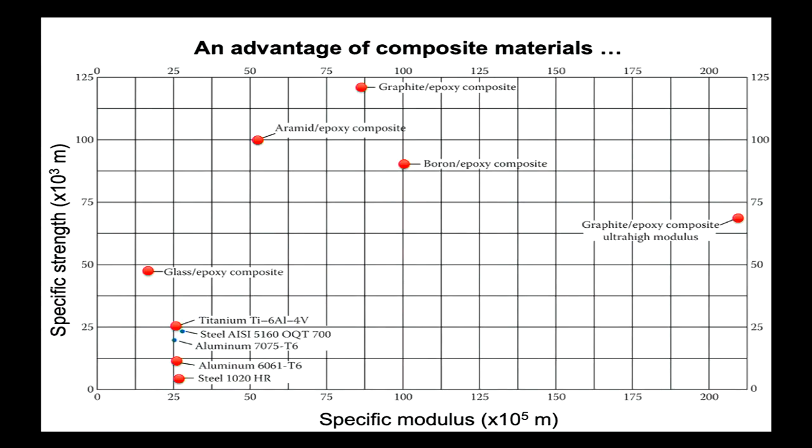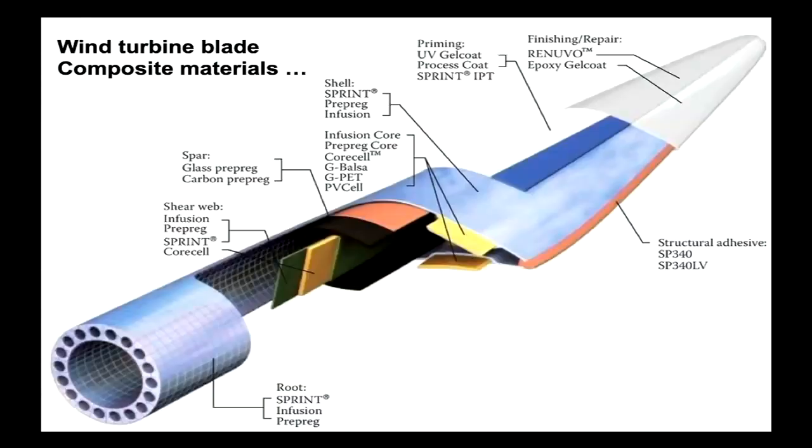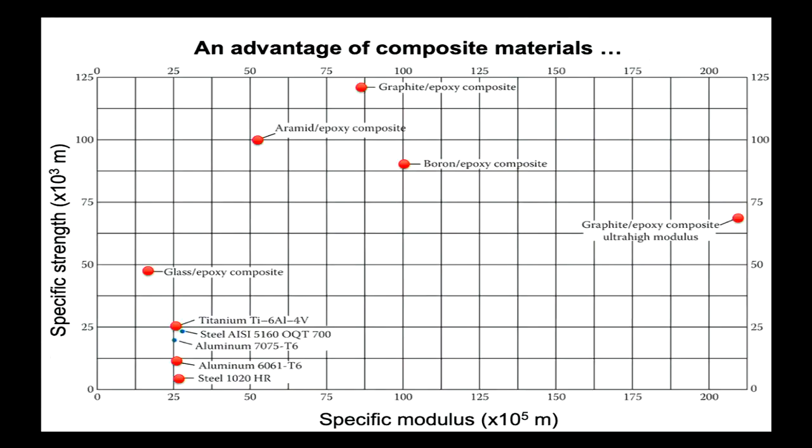This is a slide that's given you an idea why carbon fibre, glass fibre, all these composite materials are winning the race at the moment in terms of choice. I've talked about carbon fibre first thing. Why isn't that a steel or aluminium blade in toto? Well, here's part of the reason why. Aircraft, wind turbines, etc., they want high strength, low mass. They also want to be reasonably high stiffness with low mass. The overall word is specific in that regard.